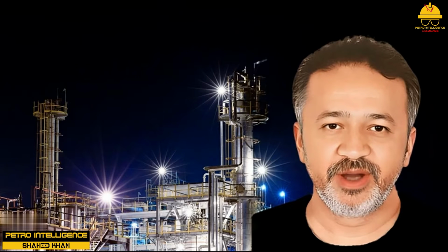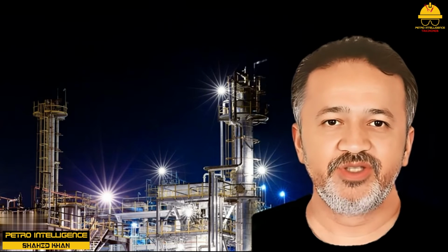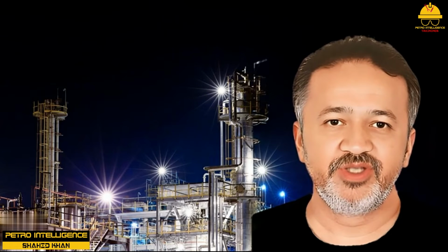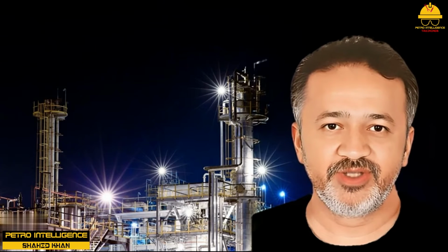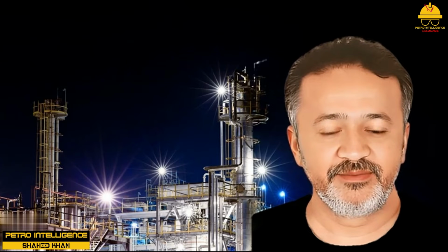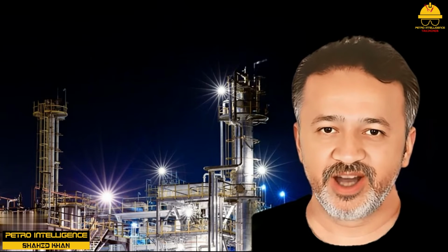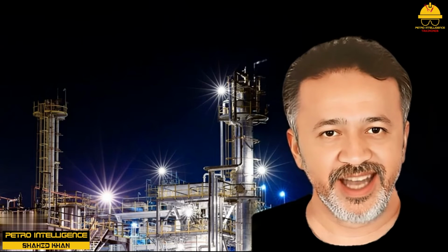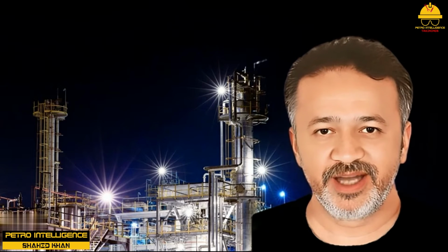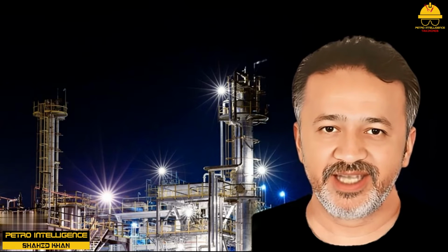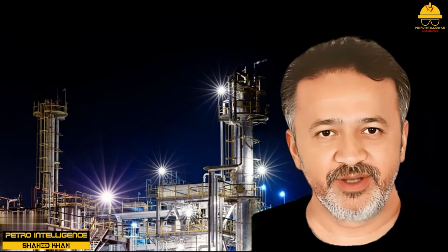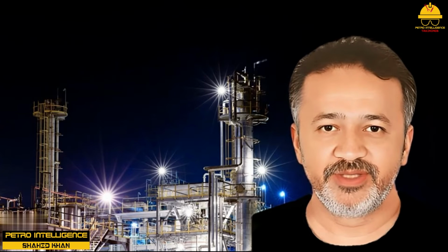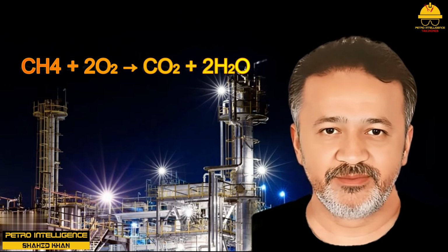Combustion. Combustion reactions are exothermic reactions that require fuel, oxygen, and heat. In this type of reaction, oxygen reacts with another material so rapidly that fire is created. For example, the reactions in a fired furnace or a boiler are combustion reactions. Natural methane gas (fuel) is pumped to the burner, mixed with oxygen (air), and ignited (heat). This reaction, which releases carbon dioxide, CO2, and water, H2O, can be represented by the following chemical equation.